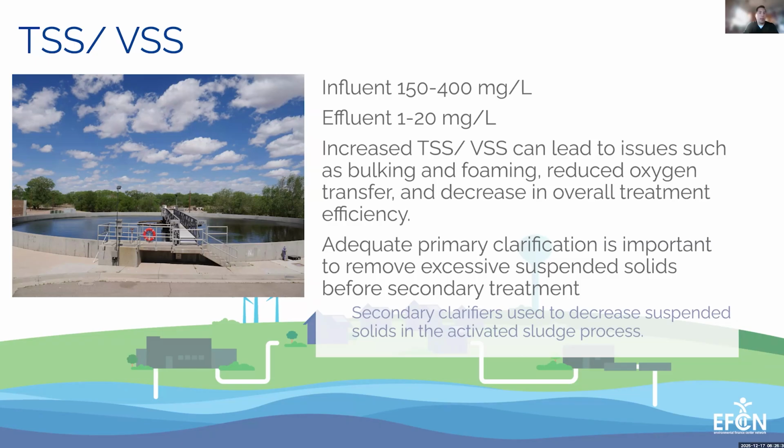The way to control that is adequate primary clarification to make sure that we're not passing solids into the activated sludge process, but also our secondary clarifiers are used to decrease those suspended solids either through the wasting or the return activated sludge as well.